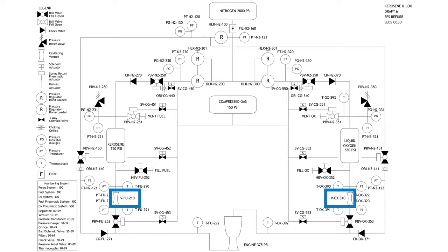Next on the list is a solenoid actuator. We use solenoid valves, where you induce an electric current through a solenoid, and it creates a magnetic field, and that magnetic field will pull up a pin, and that pin will lift up and let fluid flow underneath it. Usually that pin's blocking the way. But when you send an electric signal to that solenoid, it's going to open up and let flow through the bottom.